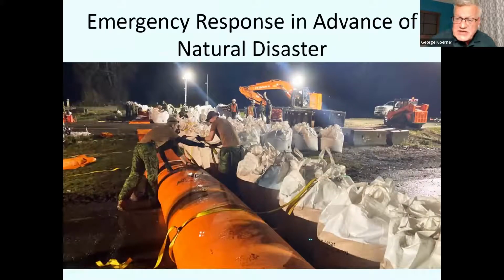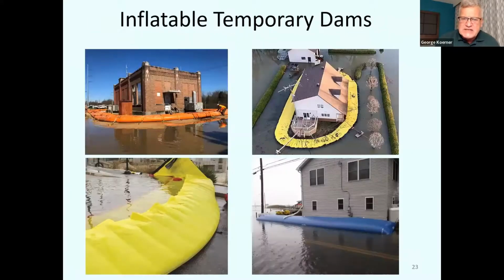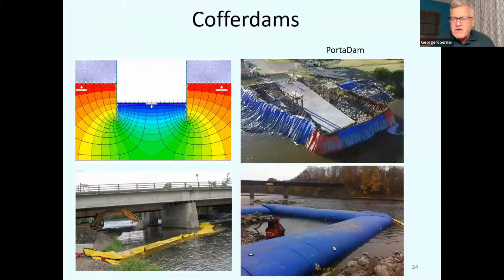I don't know the situation in other countries, but FEMA is stockpiling inflatable dams throughout the country, particularly throughout the Southeast. This is for emergency disaster relief. The National Guard is equipped to do this and has training for it. We see it even in home ownership, and for critical structures like pumping systems and electrical systems. New York City, for instance, has an entire sequence of these dams for all the subway systems and electrical conduits throughout the city. This is used also in civil engineering construction for coffer dams.